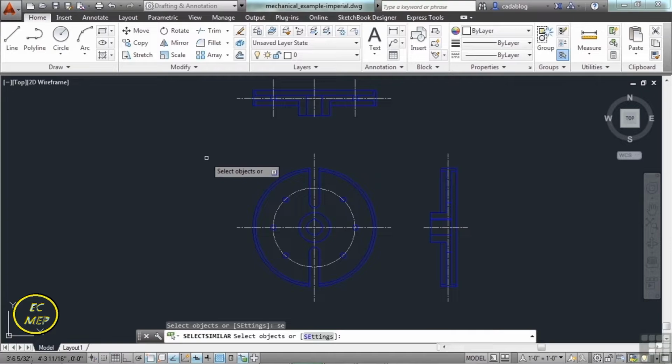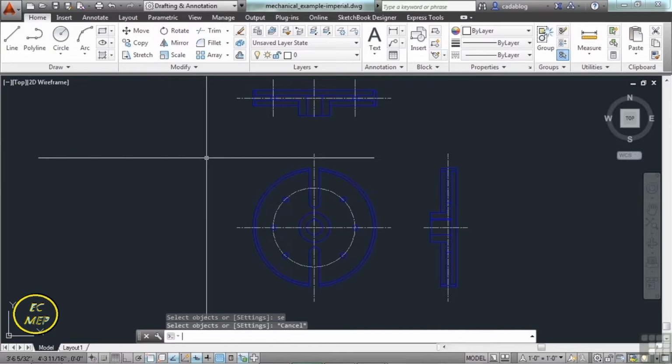And there you go. AutoCAD gives you several different ways to select objects. Remember some of those whenever you go to Start. You have your crossing window and your selection window. You'll use those most often. Plus, you can pick an object one at a time. You have the fence command. You have the Select Similar. You also have your window polygon, the WP, or the crossing window polygon, which is CP. And you have your Shift key, which you can use to unselect things. This will save you a lot of time and effort through your drawing process.